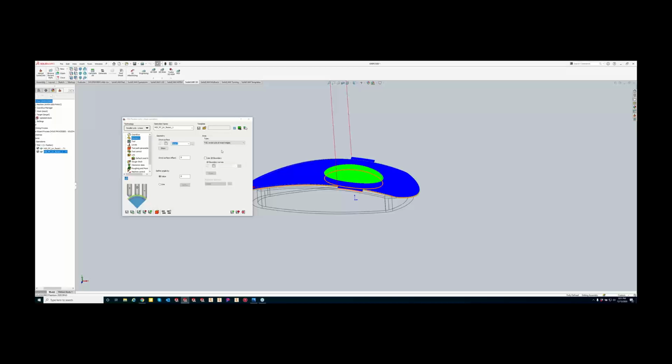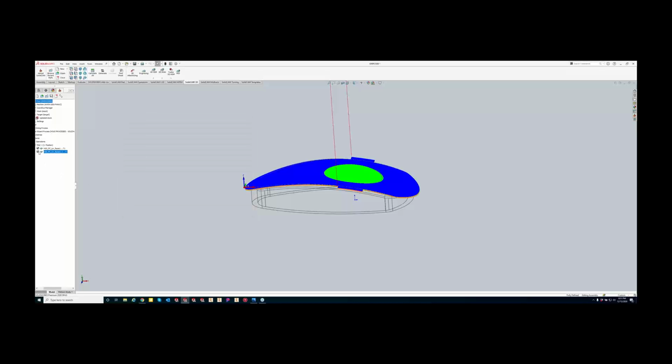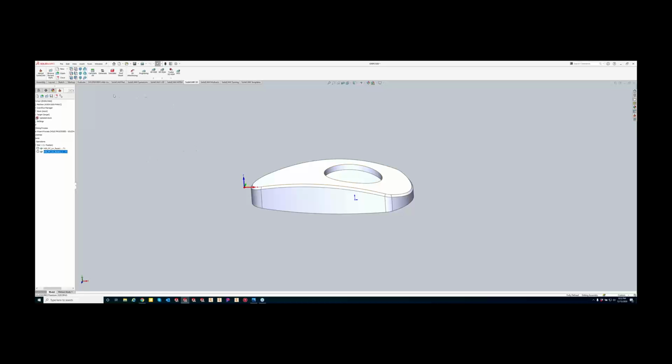I want you to fill that hole with a surface, a SolidWorks surface. So to go do our fill, right click on it. I'm going to do edit part. And we are going to go to our surface tab here. And we will do a filled surface. Okay. Beautiful. And now,